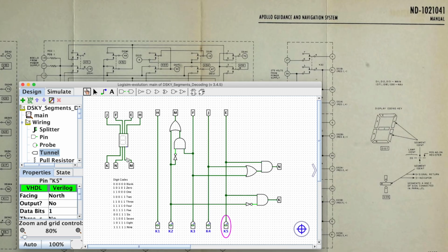I've named my segments the same as they do. Here is a relay K1, that's this relay, and this one is simple. It just powers on DS1H1, which is segment H of one particular digit. So if I do that, exactly, I have segment H lit up.